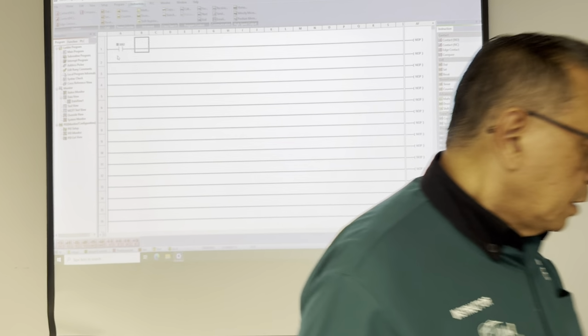Okay, now this is the conditional area. I will have an output. I will use the green light. So I click here on the output section and select output. On instruction, hit on output, and right here on this menu, these three dots, when you click on it, it's giving you access to this menu. I will use the Y001.